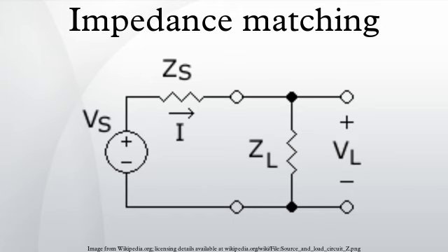In general, impedance has a complex value. This means that loads generally have a resistance component which forms the real part of Z and a reactance component which forms the imaginary part of Z. In simple cases the reactance may be negligible or zero. The impedance can be considered a pure resistance, expressed as a real number. In the following summary we will consider the general case when resistance and reactance are both significant, and the special case in which the reactance is negligible.